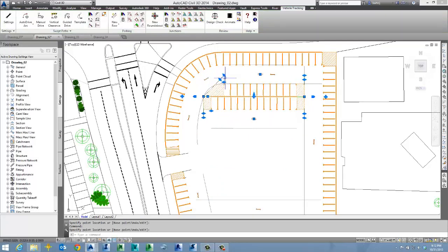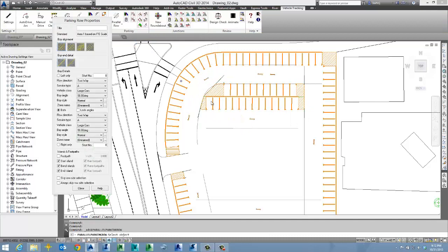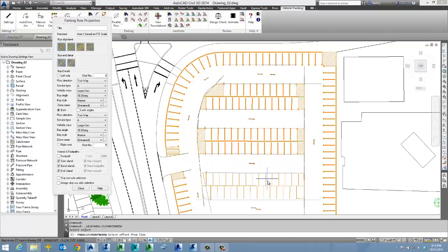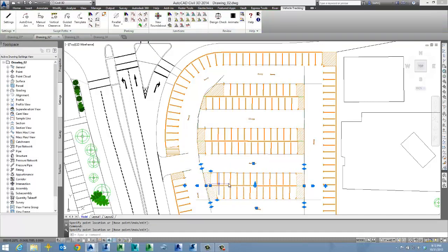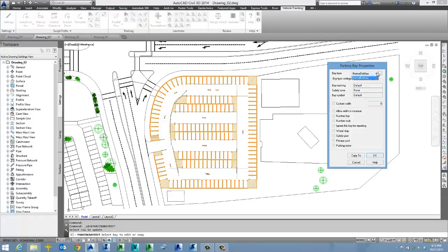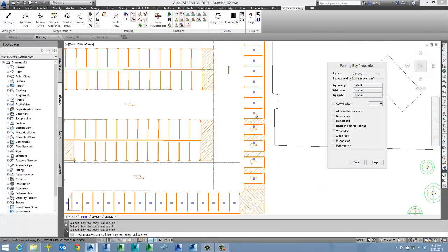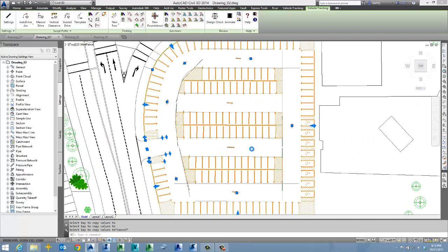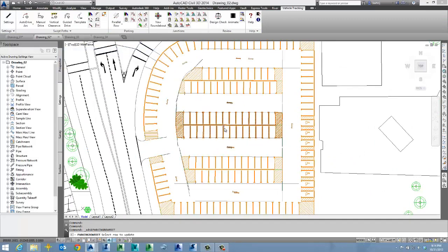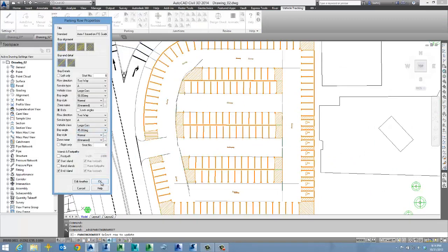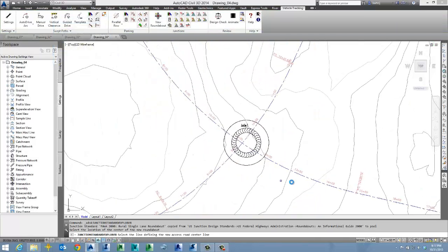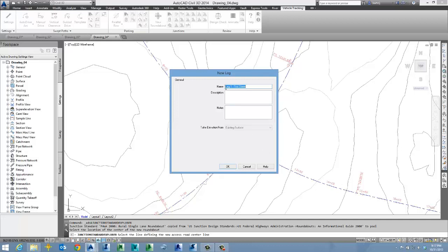With Autodesk Vehicle Tracking, simply select a standard for the spacing and size and begin sketching in the lots. You can easily offset rows of parking in larger spaces or draw new lines parallel to the sides in smaller ones. Adjustment for the islands to better regulate flow and parking angles can all be handled with simple grip functionality. Even toggling between standard and accessible spaces just takes a few clicks, and vehicle tracking even drops in the striping and symbology.